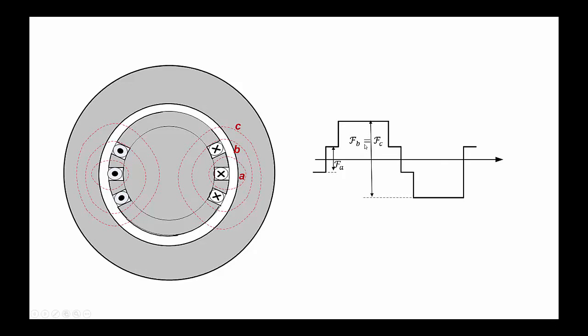A stepped waveform like this one would have a fundamental and harmonics, but of course the harmonic content will be better, with fewer high order harmonics than the single step square wave. Anyway, by certain design techniques, it's possible to obtain an MMF distribution which is very close to a sine wave. So close, in fact, that it's common practice to assume it's a sinusoidal distribution. We will deal with such winding arrangements when we consider special machines.